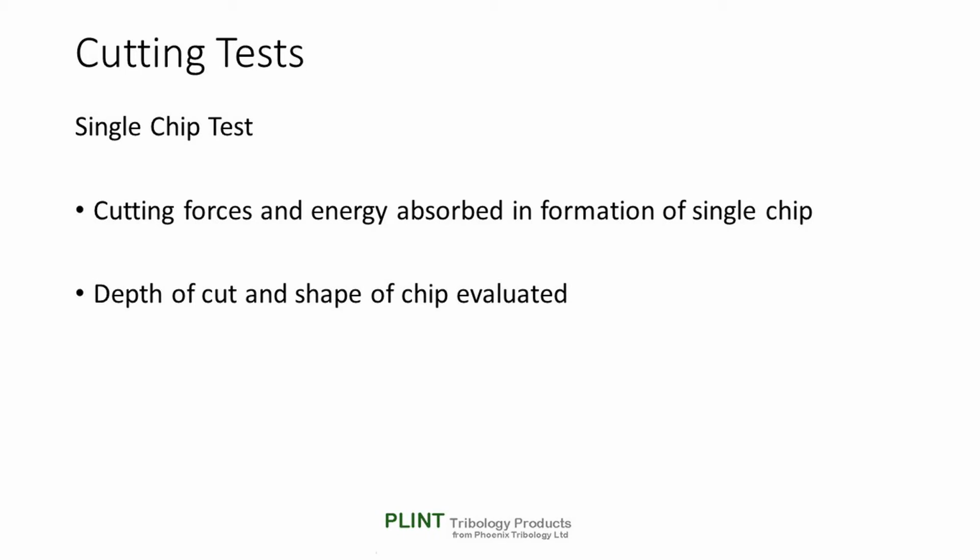A number of experimenters have performed tests to investigate the forces and energy involved in the formation of a single chip in a machining process. One approach is to use the equivalent of a small Charpy tester, but with a machine tool tip secured to the bottom end of the pendulum.